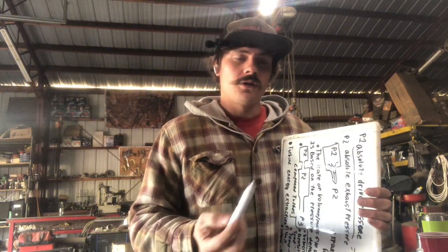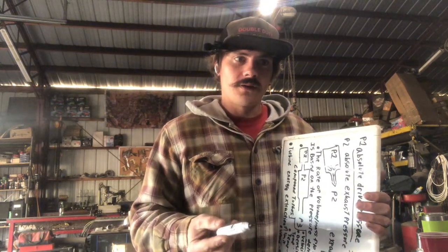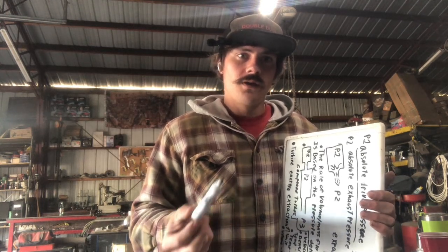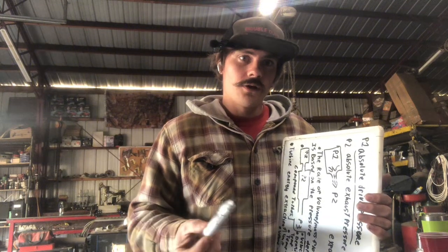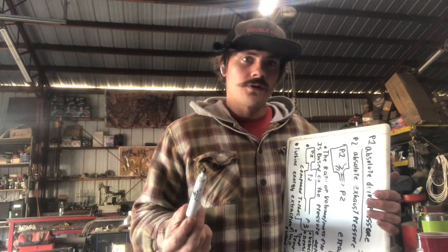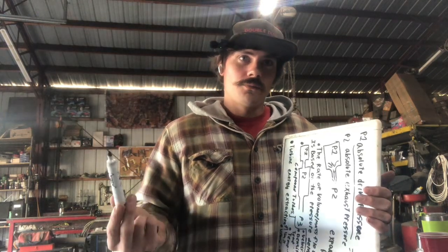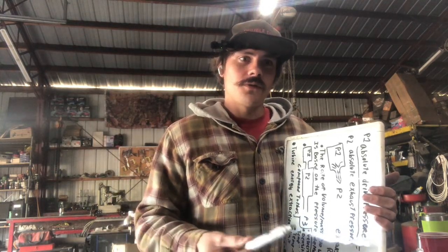And then as you close down the slide valve and raise the exhaust pressure, the vanes compensate to raise the drive pressure to maintain enough expansion ratio energy to hit the same boost target. And because that target just so happens to be still pretty much at the Mach limit of most turbine wheels, there's no change in the power.